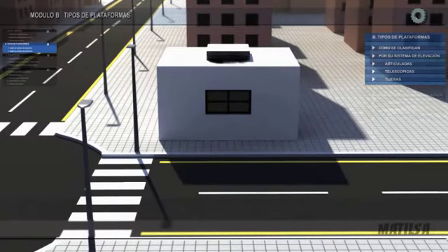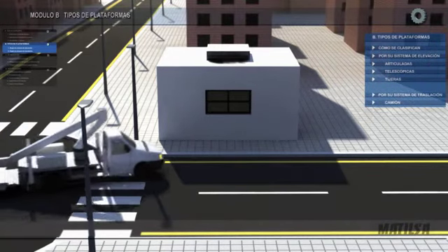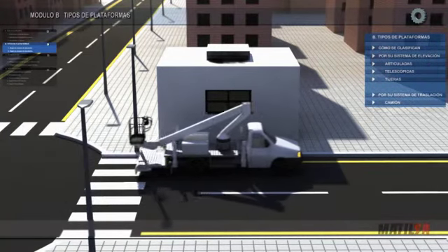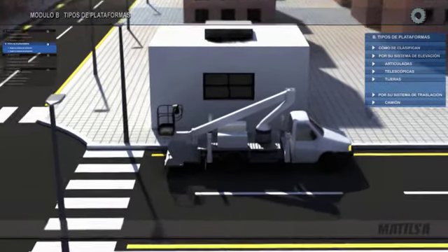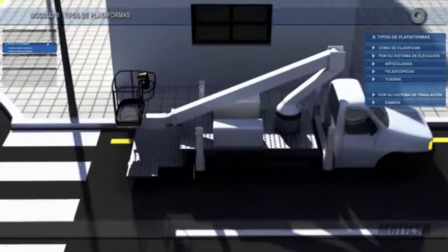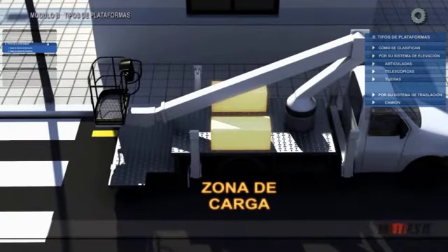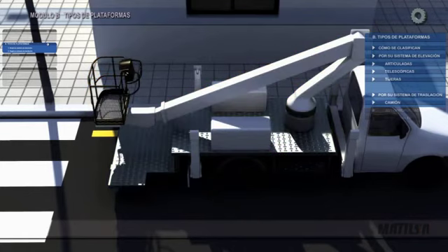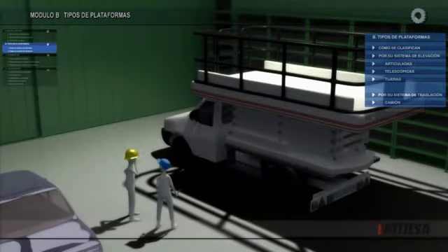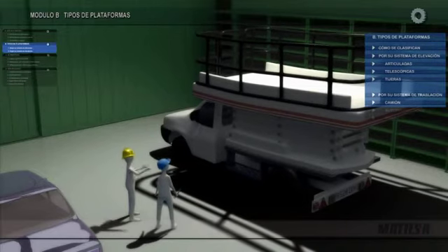Features of the different transporting systems. Truck-mounted platforms. These platforms are mounted on a truck. It should be taken into account that as it carries an elevating platform, it does not allow for an excessive load on the box, since the maximum allowed load is occupied by the platform itself. And the same goes for the amount of space. The main headache for the manufacturers is the struggle against the weight, giving a higher working height.